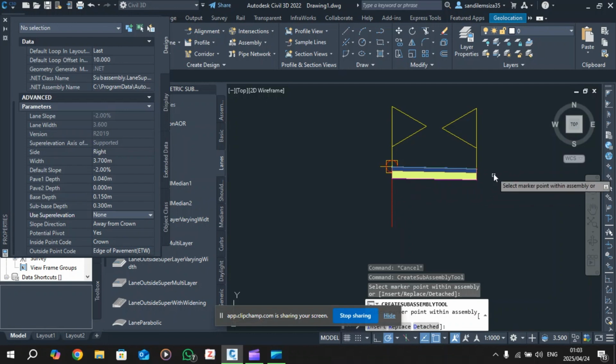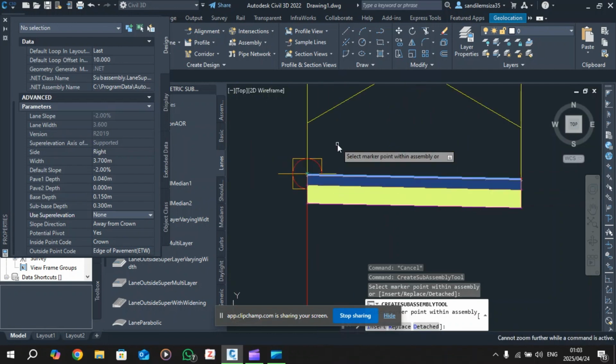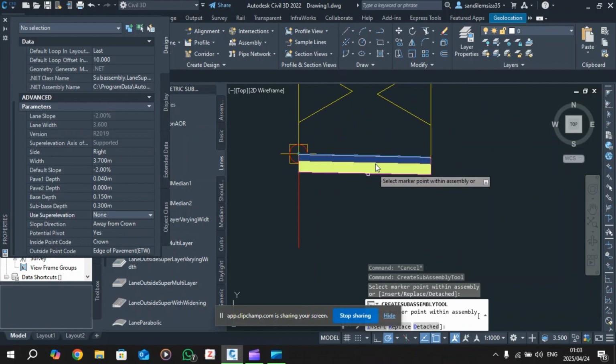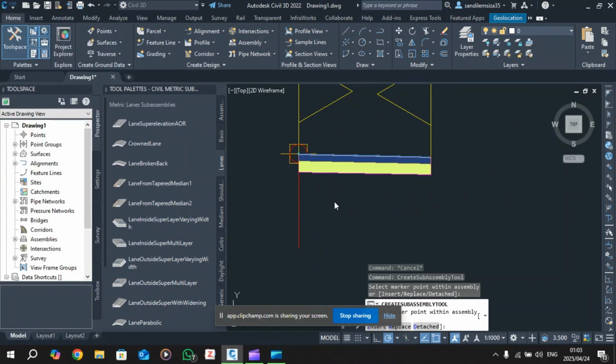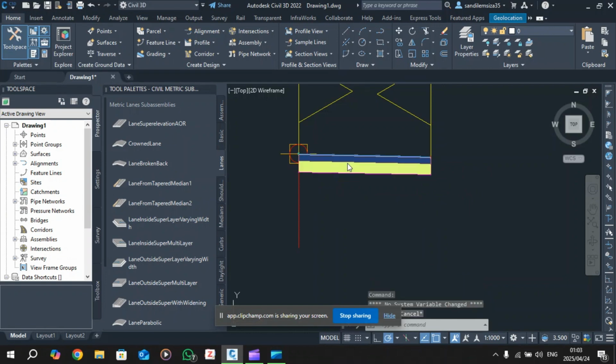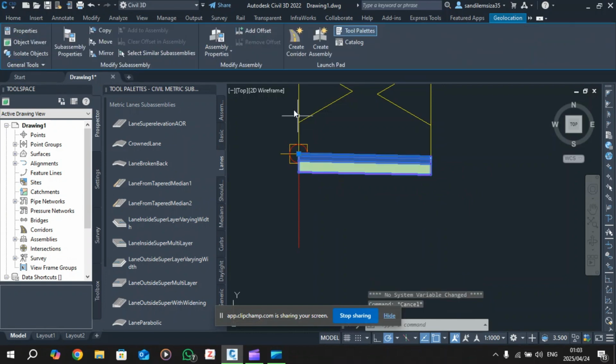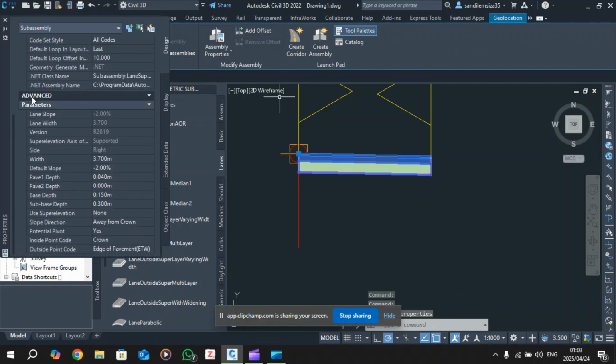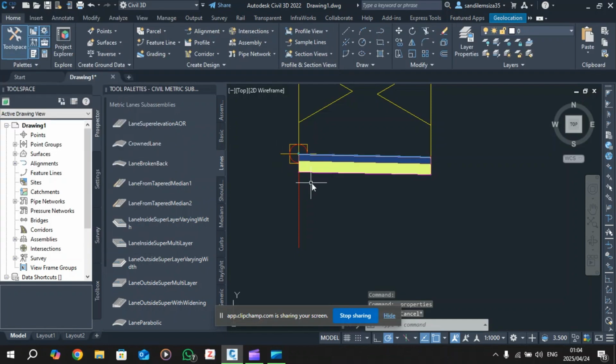And as you can see, this is your lane. So this will be your lane. You can change the properties of these after adding. You just need to press escape, and then afterwards you just click and you then go to your properties. Again, the ribbon will change. So you just need to go to properties and change what you need to change under your parameters.